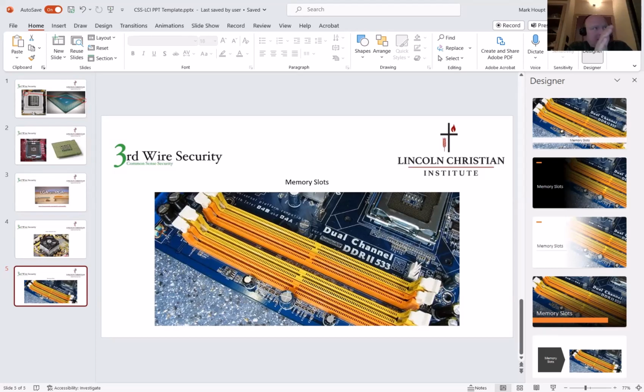It's actually slightly off center, and if you had a memory chip or a piece of DIMM in your hand, you would see that it's slightly off center. Again, this is designed only for one purpose, and that's why you cannot put it in backwards. You cannot put it in wrong unless you are forcing it.